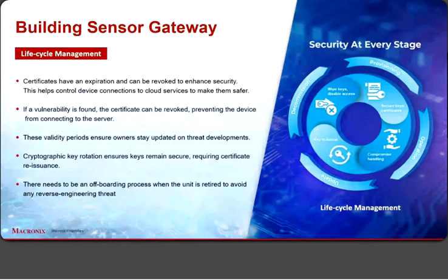Cryptographic key rotation is actually pretty common, and it ensures that the keys remain secure, while requiring certificate reissuances as well. So through the life cycle, you're going to have continued over-the-air updates and continued re-provisioning of credentials, keys, and other information from these cloud service providers. And so there needs to be an onboarding process where the unit is retired to avoid any reverse engineering threat.